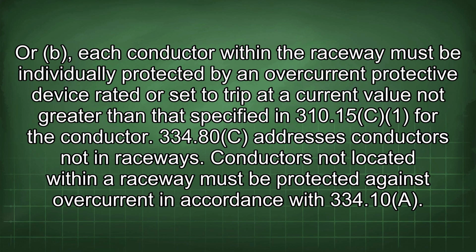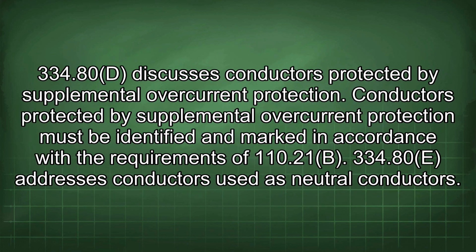334.80(C) addresses conductors not in raceways. Conductors not located within a raceway must be protected against overcurrent in accordance with 334.10(A). 334.80(D) discusses conductors protected by supplemental overcurrent protection.